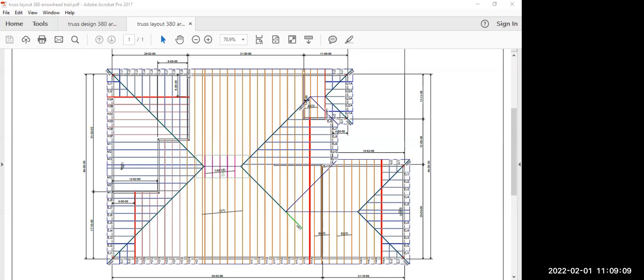But anytime there's a beam, in this case right here in the garage, you may be able to picture that, if you have a garage, there's a giant hole in the wall. In that case, I had to have a beam over the top of it to support the roof. But that took a lot of weight on top of that beam, and it put quite a bit of weight over here at the side. So I had to beef that footing up. It wasn't large enough, it's only 12 inches wide. I had to beef that footing up to 24 by 24 to be large enough to carry that load. And there's a few beams in the back, so I have kind of big footings underneath the house too. Notice this one's really big, 34 by 34 by 10 inches. It's carrying lots of the roof weight, basically.